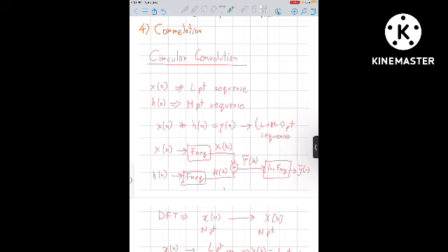So what we often do is convert the signals into the frequency domain. x[n] and h[n] are converted into the frequency domain, we obtain X[k] and H[k], and we multiply the two in the frequency domain. The resultant is, suppose, Y tilde of k, and we perform the inverse transformation to get back our signal in the time domain, Y tilde of n.